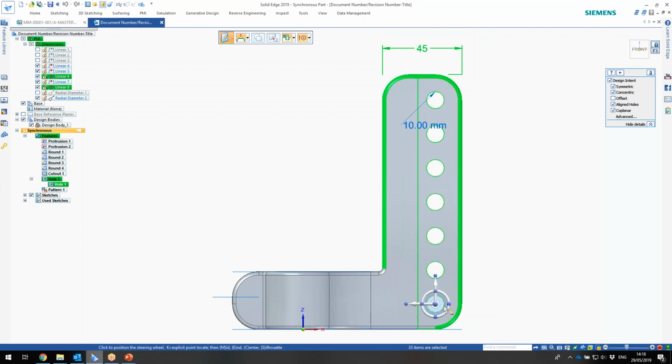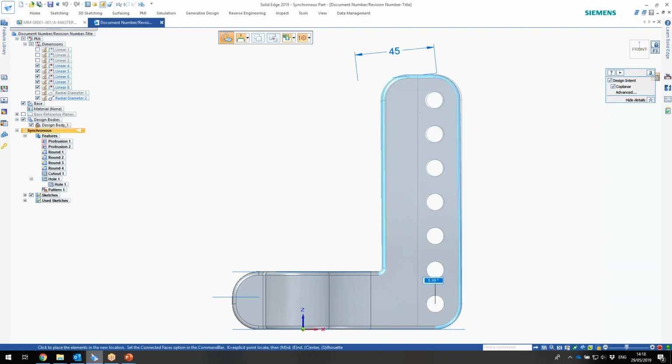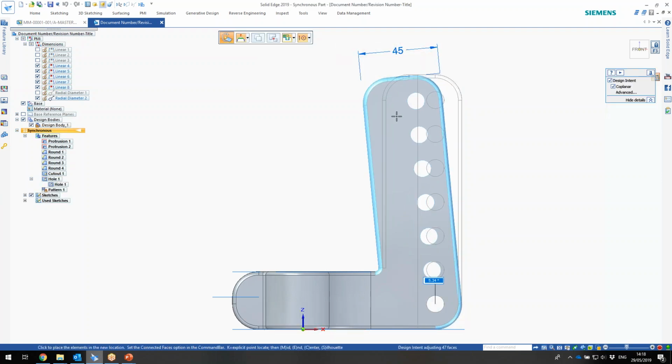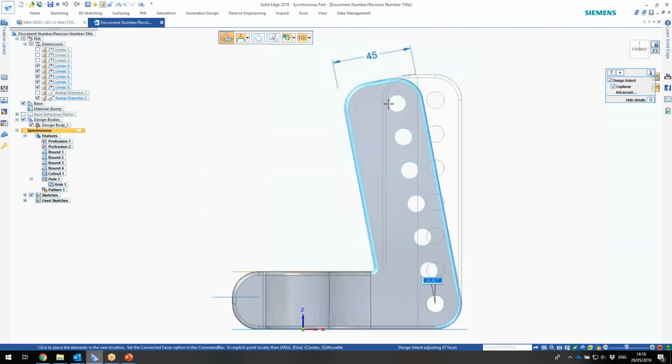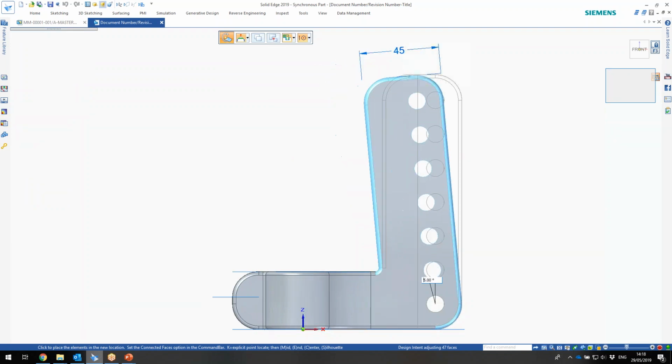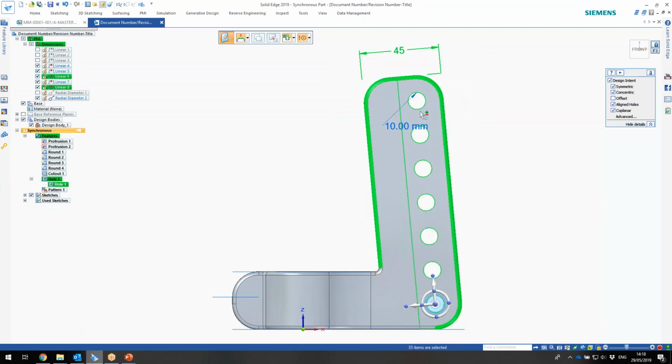You would have had to plan this from the beginning. But using the 3D steering wheel, I'm pivoting it from this lower hole. I'm going to adjust it 5 degrees. Now the system will let you know when you can't go that far, because you're going to start affecting the slot down in here. So I know I need to put that to 5 degrees. Keep all those holes in alignment and move those across.